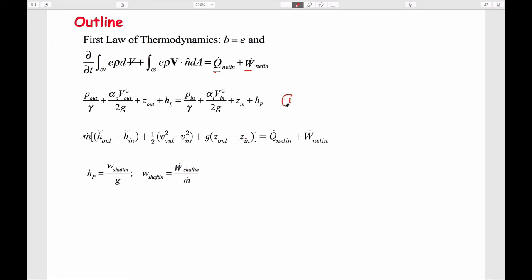They're both essentially the same equation, but one is written to include enthalpy and one assumes that enthalpy is very small. They have to be written, as you remember, this is actually written backwards from what we often think about. They're both one-dimensional equations, and they rely on velocities downstream or velocities out, and a velocity in, always positive.